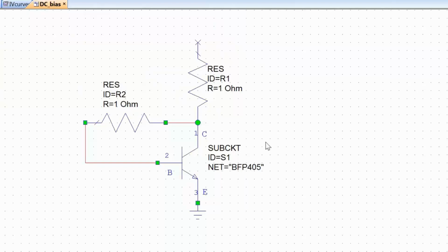We'll talk a little bit about why this arrangement is chosen and work out the values of the resistors in a second, but first of all we have to get ourselves a DC power supply. Because we want to obtain a collector to emitter voltage of 2 volts, a power supply will have to be somewhat higher than that. Usually if you choose it to be about twice that, you get good stability for the